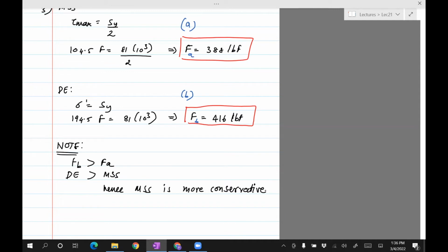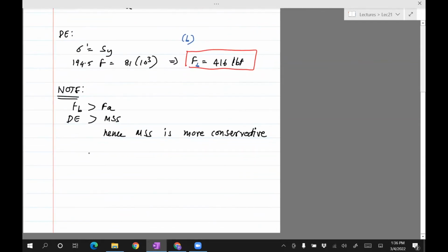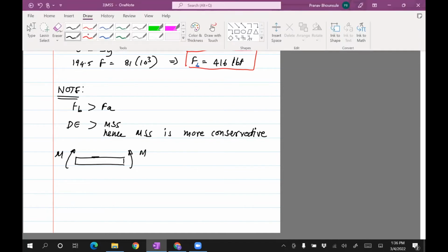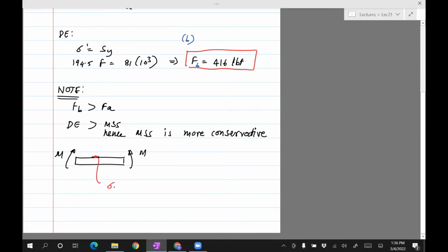Professor, a quick question. Yeah. I just did not understand why you said sigma z is 0. Sure. So when we talk about loading a beam like this, the stress in this direction on top is maximum, and that's My divided by I. And when we say that's the maximum, the stress in all other directions, that is the normal stress, is 0.